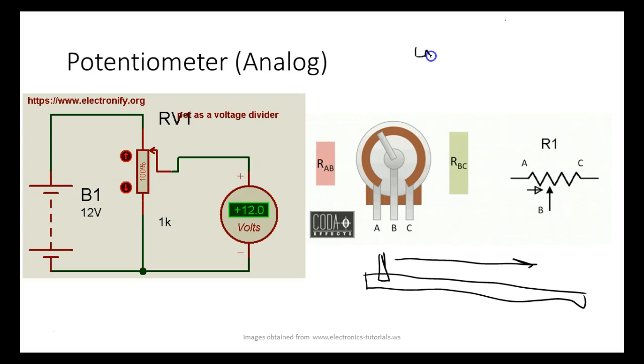I don't know what the other part is. So we have one gear that's laid out. It's like this, right? And then we have a rotary gear that meshes with this. And then as the gear turns, this moves. So I could take this and move this, and turn this, and it would cause this to move back and forth. Or I could take this and move this, would cause this to do what? Change directions. So when you see a linear pod, if it's a bigger assembly, you don't know if it uses a rack and pinion or something like that. That makes sense?